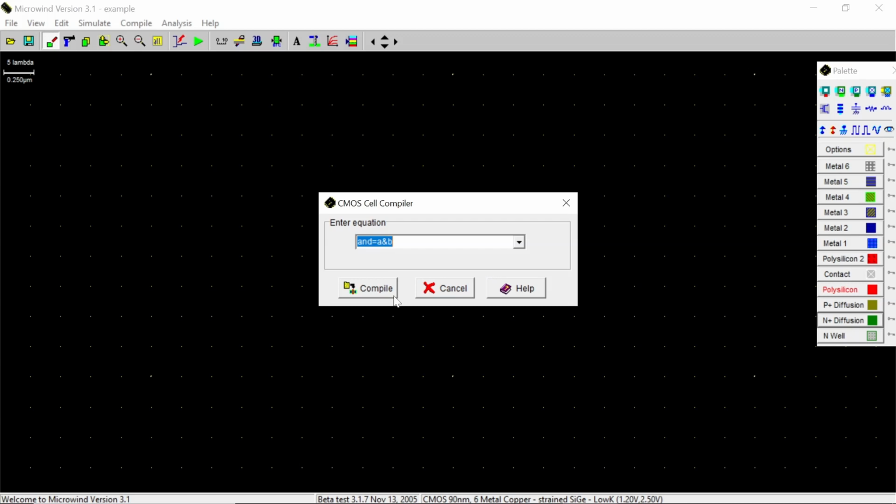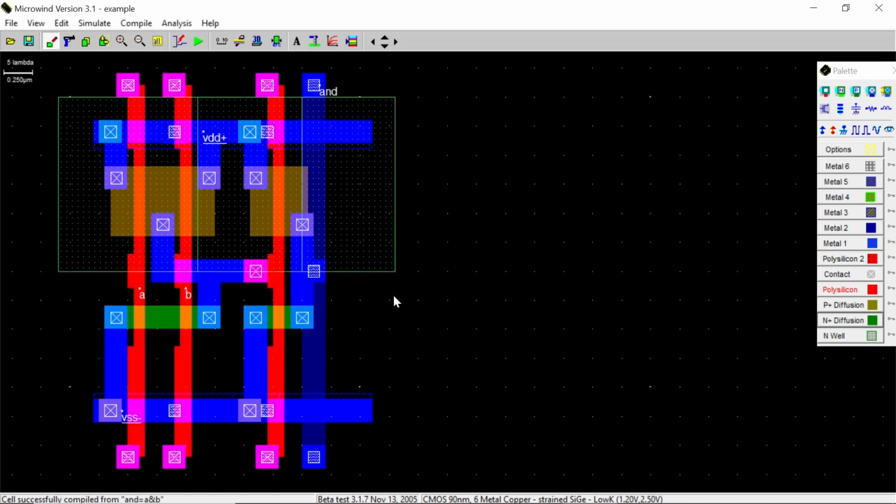This doesn't immediately show us any waveforms because, at this stage, we are essentially creating the blueprint for our gate without specifying how it's tested. Look for the Show Palette button. This tool allows us to introduce inputs and outputs into our design. Click on it. We need to simulate how our gate reacts to changes over time.